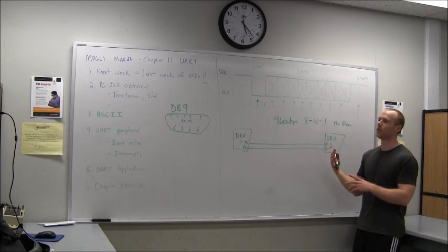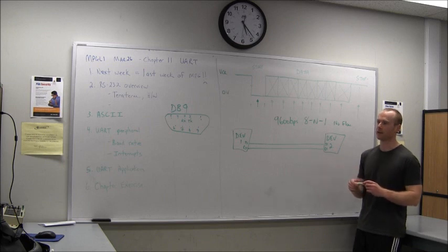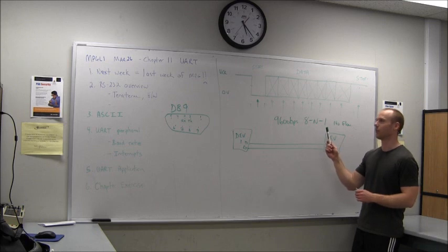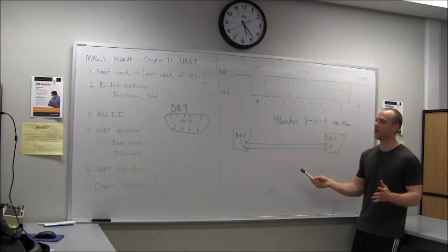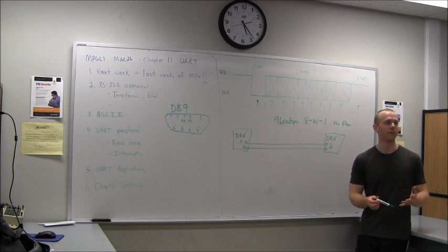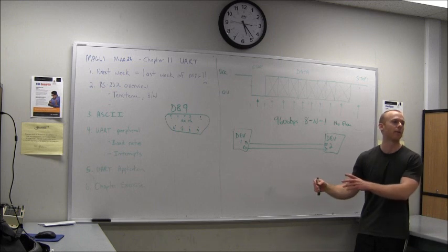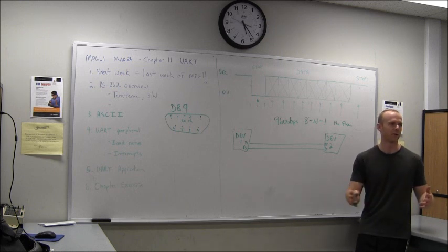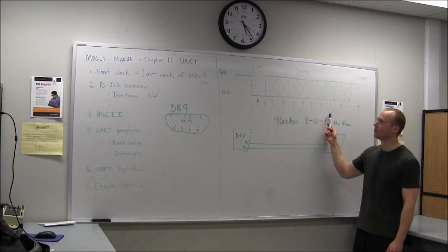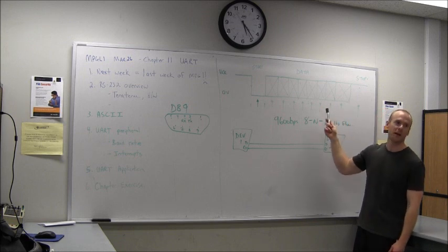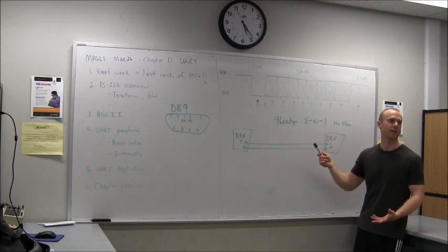So we'll see when we get to the ANT radio, their communication, even though we're not going to do it with UART, they'll still send a bunch of data bytes that don't have individual error checking on them, but a message might be 15 or 20 bytes, and you'll have a checksum in there, and you can verify your message that way. If you start putting a whole bunch of parity bits and other error checking in here, then it just adds to your overhead.